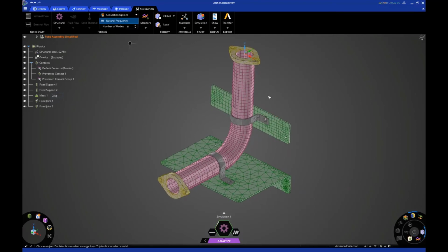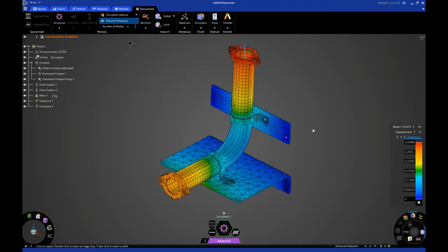If this mesh is not satisfactory, you can pause the simulation or wait for it to run. As you can see, it's already finished running. We have the green line all the way across, and then apply a different mesh fidelity later on. Okay. So here we have it. You see mode 1, mode 2, all the way through mode 6.